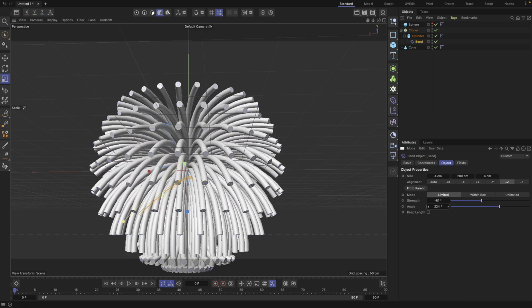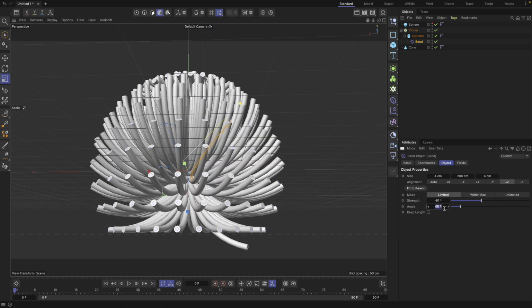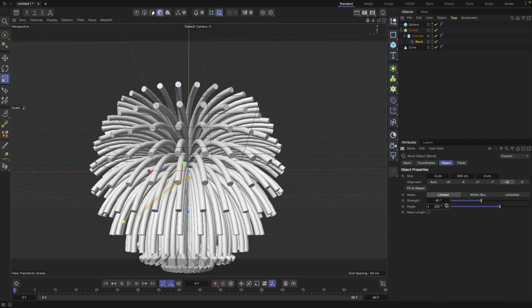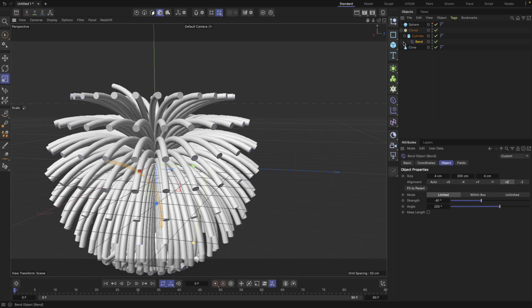So I can also make them point downwards. Like if it's 45 degrees, I need to add 180 degrees, for example, so that it's faced downwards, right? So I can do math operations in those areas also. I hit plus 180 and hit enter, and you see that immediately that math operation is done here. So you can do multiplication, subtraction, division, all those math operations here. See, so you can always combine these things with each other.